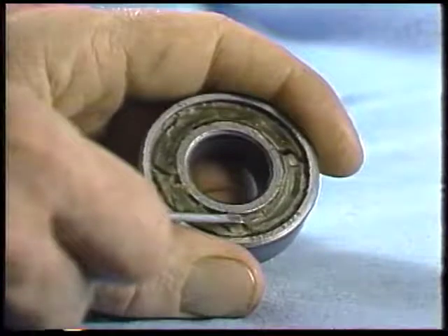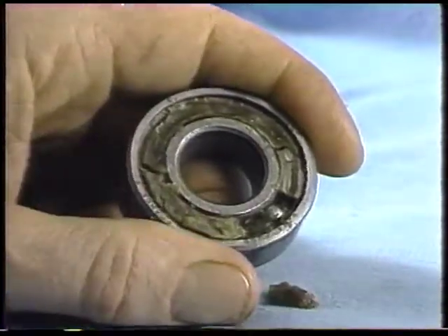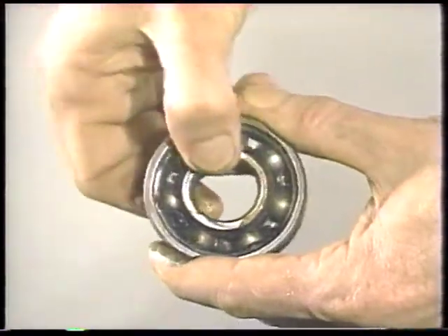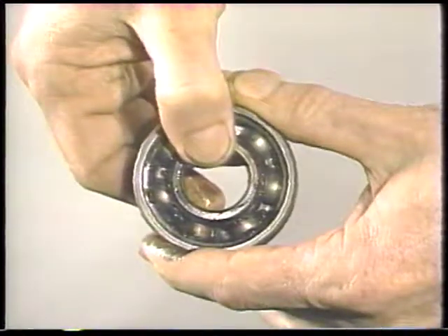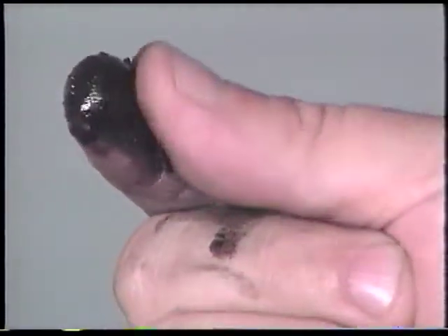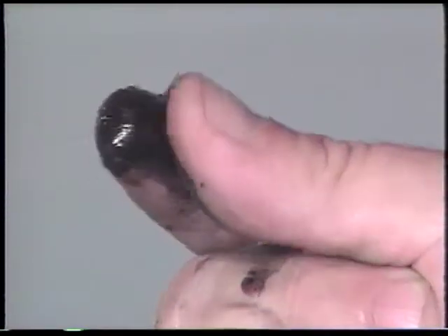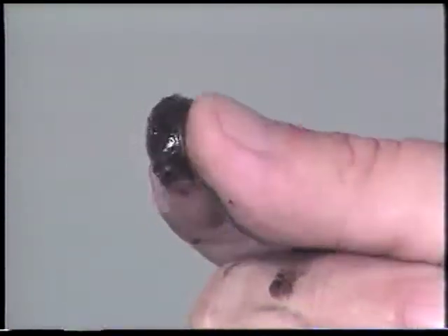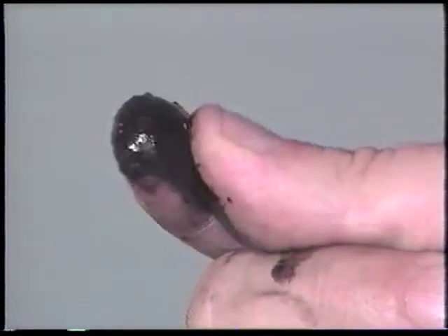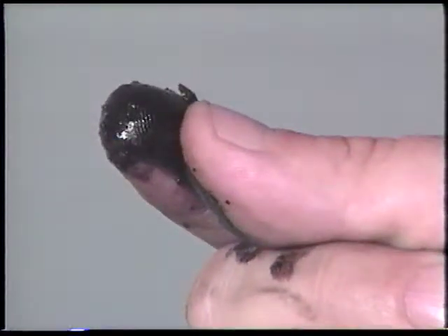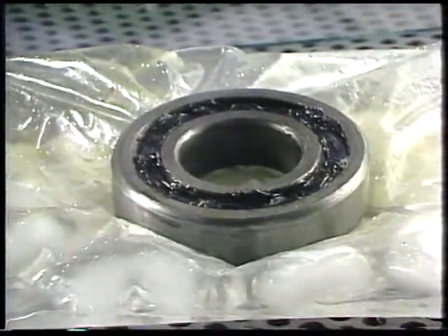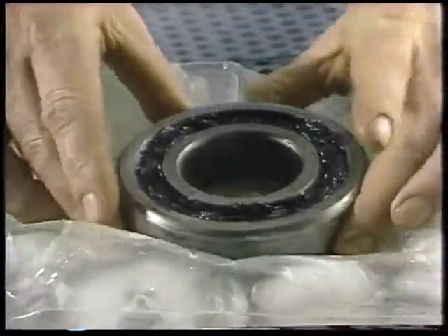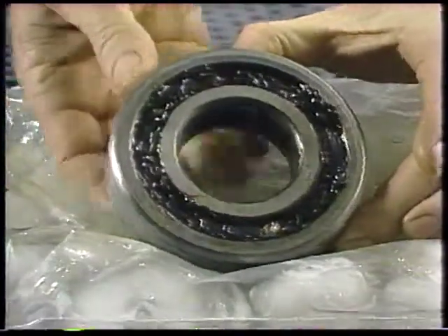Note the consistency of the grease. If it is hardened, it should be replaced. Note the color of the grease. If it is darkened, it may be oxidized, or it may contain particles, or it may have water in it. Take a little of the grease and rub it between your fingers. Check for any water present. You'll see it in small droplets. Look for any particles you can see. Very small particles will make the grease feel rough or gritty. Grease that is burned or carbonized means the bearing has been running very hot for some time. Any of these conditions may indicate the bearing has been damaged.